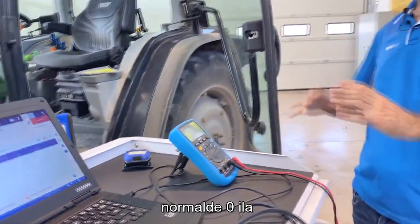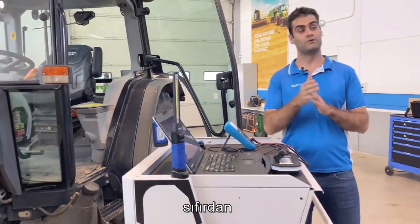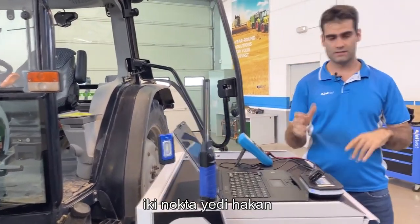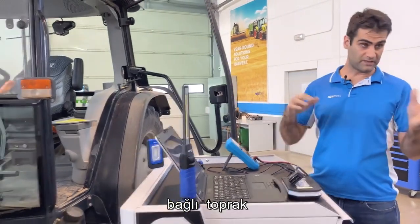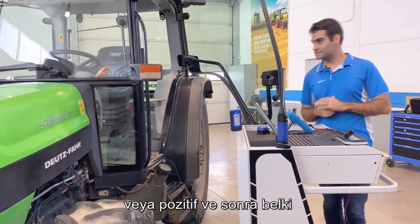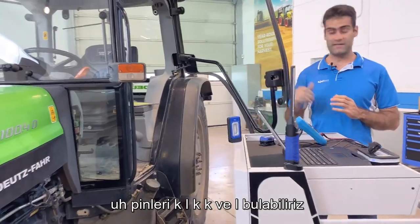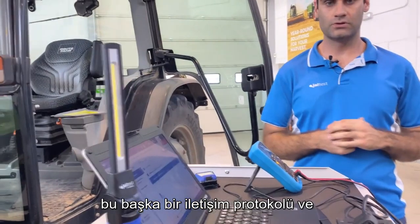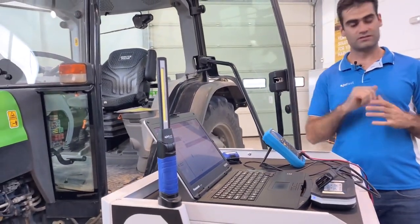Normally, we are going to have from 0 to 12 volts. Talking about the CAN lines, we are going to have from 0 to 5 volts, an average of 2.5, 2.7, depending if it's CAN high, CAN low. For power supply from 0 to 12, depending if it's ground or positive. And then we maybe find some K-line pins, K and L. It's another communication protocol, and also we can figure out if it's there using the multimeter.